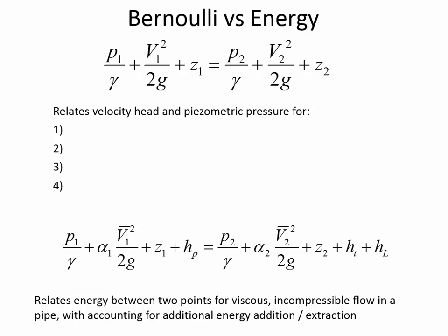All right, now let's look at this velocity head term, v squared divided by 2g. The first thing is you'll notice that there's an alpha term in front of that. That's called the kinetic energy correction factor. And on the next slide, I'm going to show you some more information about the kinetic energy correction factor. But here's the good news. Usually we just assume that alpha is equal to 1. It's under specialized conditions when it's anything other than 1.